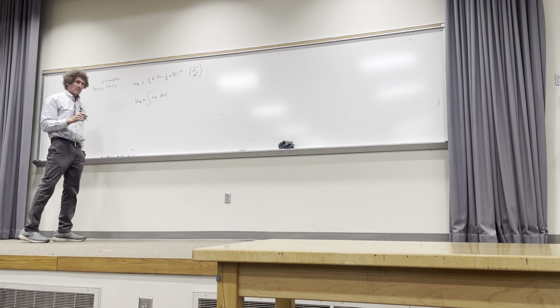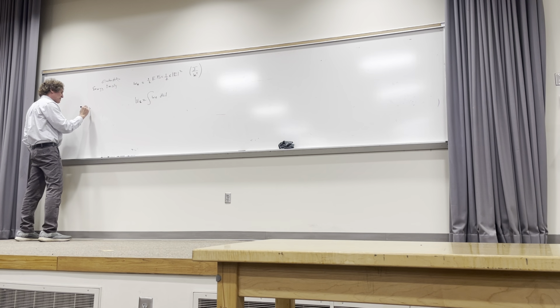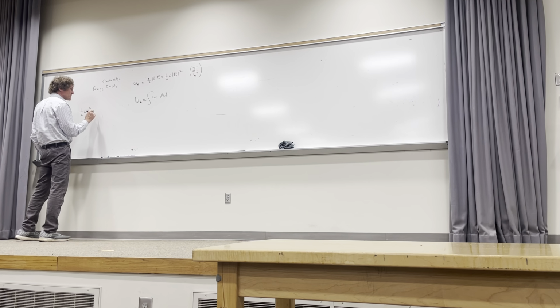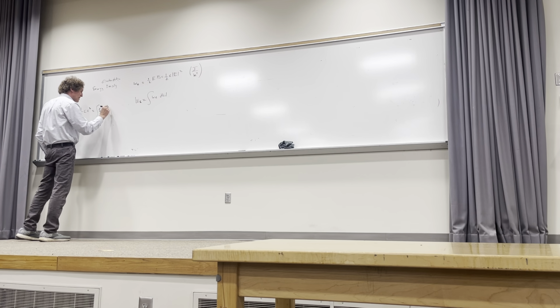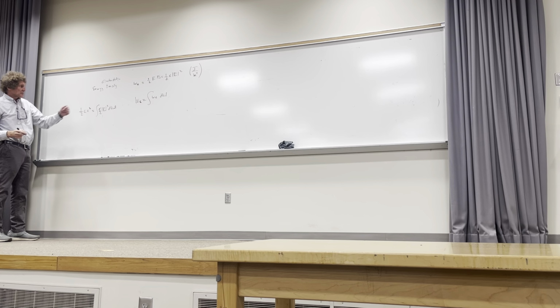That's the total energy. But we can get capacitance by knowing 1/2 CV squared. Remember, the voltage in this equation is the voltage difference between the plates. That would be equal to the integral of epsilon over 2 times the magnitude of E squared over the volume. We can integrate the energy density over the volume of space that it exists in, and then equate it to 1/2 V squared times C, and really solve for C here.